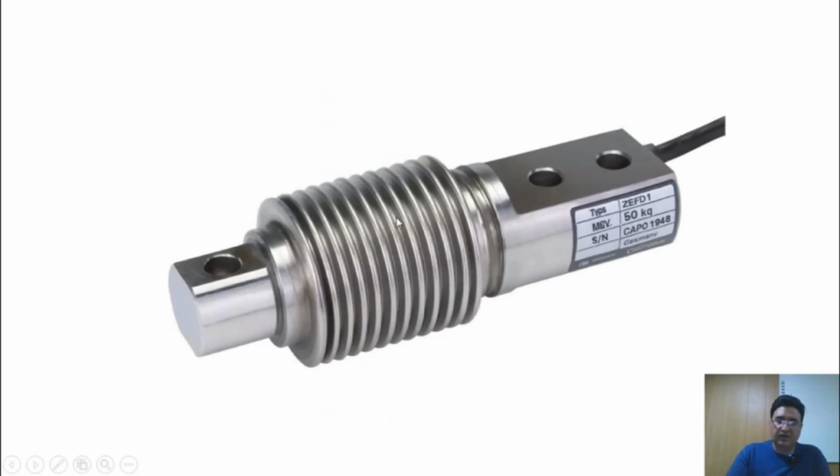The difference between these bending beam load cells and shear beam load cells is as follows. These are the grooves that you can see here, and these grooves are designed to eliminate the lateral forces applied to the main body of the load cell for us. This type of load cell is usually used in conveyors or places where dynamic weighing is needed. And in fact, one of the good features of this load cell is that it has a very high frequency response. That's why we can use this load cell in dynamic weighing applications.